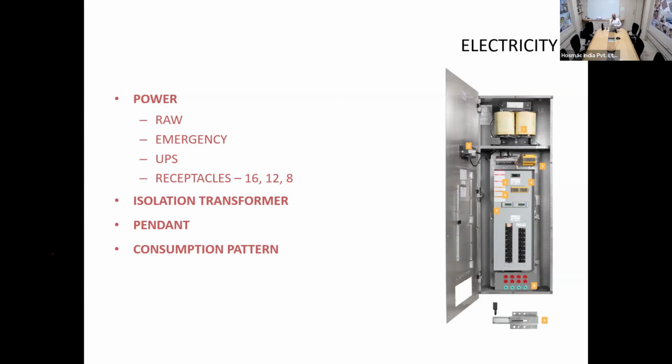Something we cannot afford to have in an operating room, which is why we have a contraption called a medical grade isolation panel. This is something that allows the earthing to be non-grounded. It's only when the fault occurs that it will get converted to conventional grounding. Thereafter, if there is a second fault, of course, it's going to trip. But you have a sufficient window period within which to identify the fault and rectify it, so that you can continue working on the patient without a compromise up to a point in time.